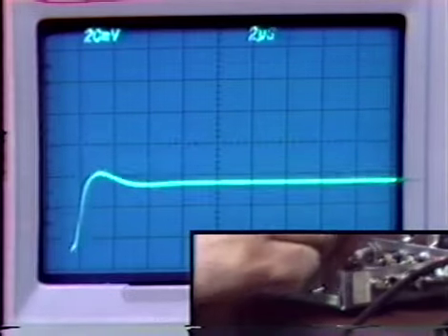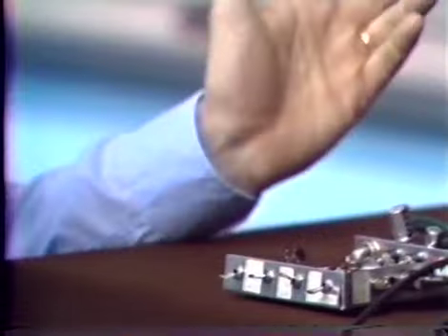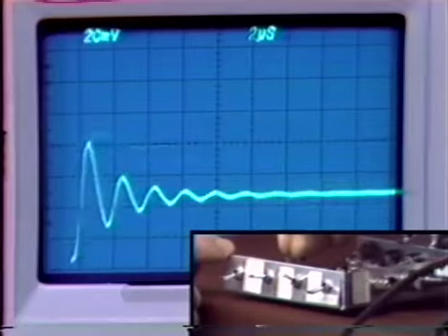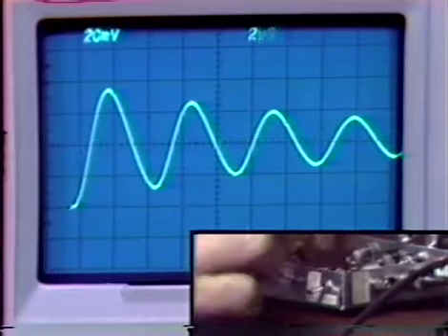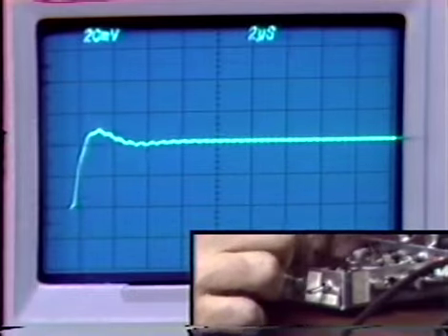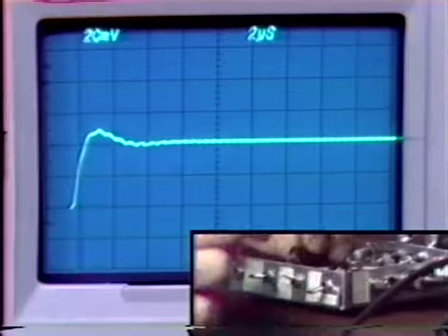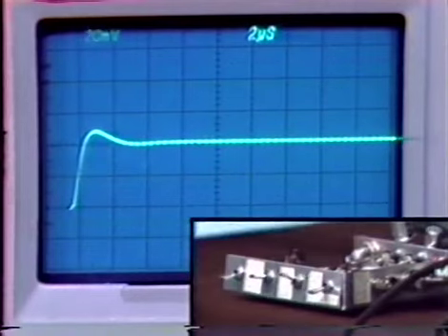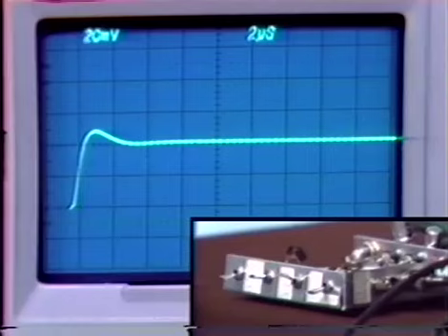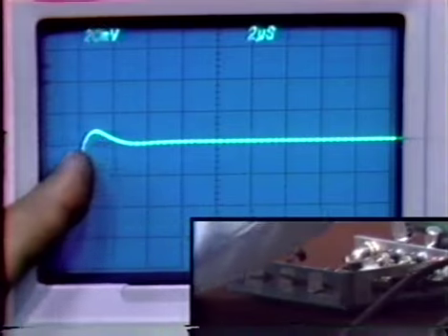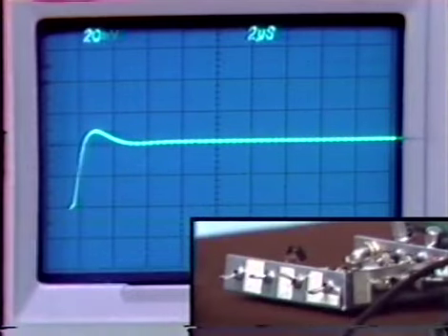Let's do it once more. Let's take out that capacitor. The teeth come. We add the capacitor back in. Simply move this lead over. The minor loop gets much better behaved, and we really haven't significantly changed the overall features. We haven't changed things significantly in the vicinity of the major loop crossover.